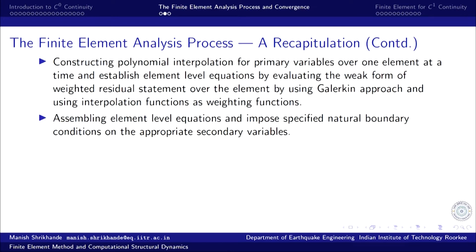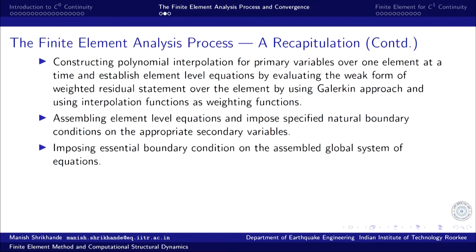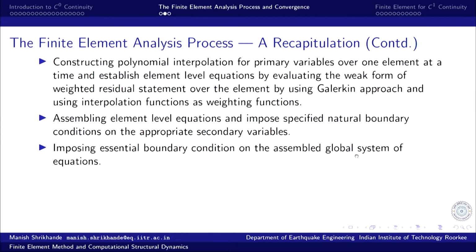And also at the element level equations we also impose the natural boundary conditions, whatever are the natural secondary variables, if those are prescribed, those are imposed at the element level equation, and subsequently the element level equations are assembled into global system of equations, and then the essential boundary conditions are imposed on the global system of equations. And of course, for the assembled global system of equations, if any transformation is required, that has to happen